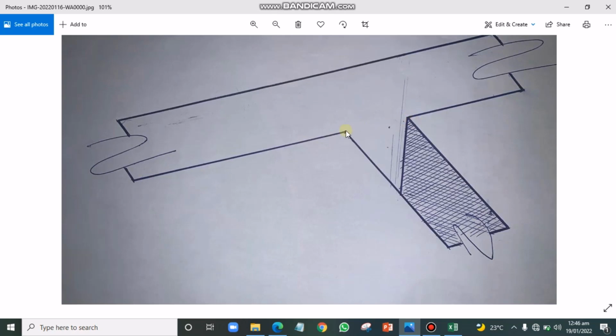So there is always no need to put a wood when you have an intersection between two walls. So look at this wall or this trench intercepting with this other trench. In this section, the wood will be placed, or the earthwork support will be placed from here to this place. But along this second part of the wall, you will realize that when you place the earthwork support from here, you will stop here. Then you will now start over from this place and continue down to this place.